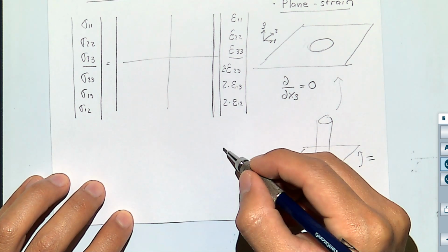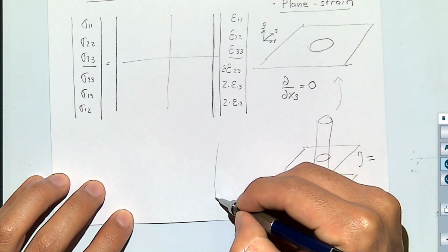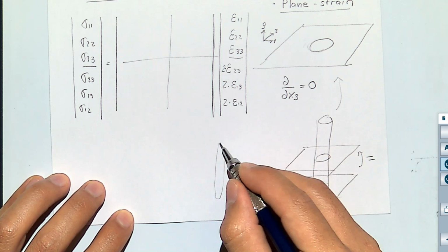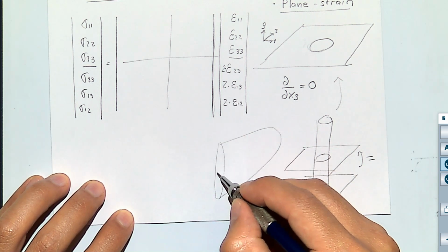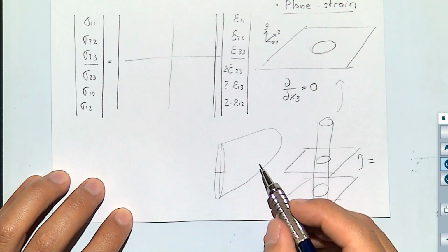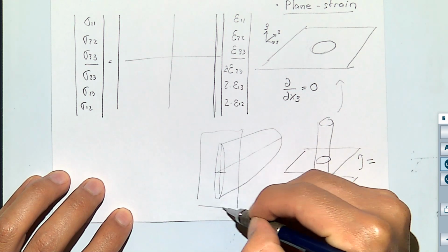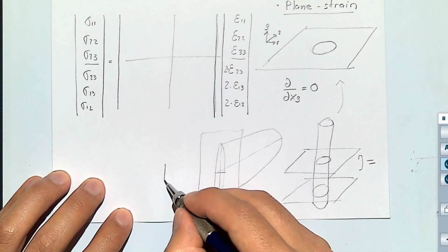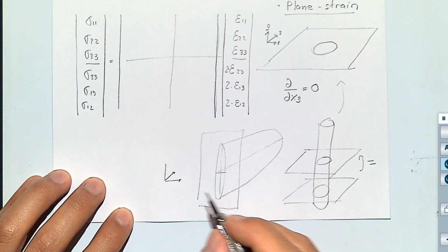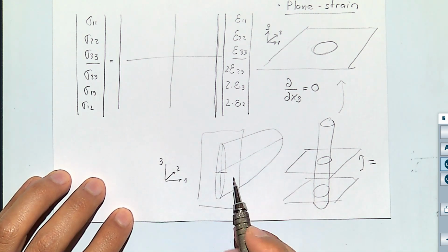For a fracture, what we're going to assume is, let me see if I can get this plot right, a plane state of stress along the axis of the wellbore, saying that the medium is just going to deform, in this case, in direction 1 and in direction 3, but it's not going to move. There's not going to be any displacement in direction 2.